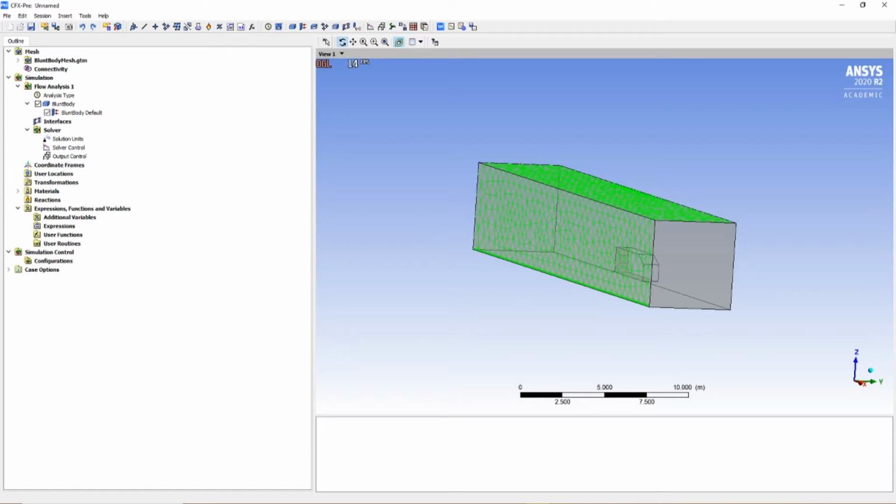There you go. Now we're going to create the boundary conditions for this problem. The simulation requires an inlet and an outlet, which we've already done many times, but we're also going to use walls for this problem. In CFX, any face that you don't set up a boundary condition for is going to be interpreted as a wall.